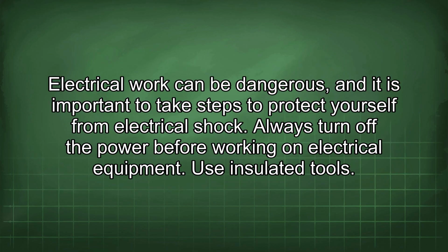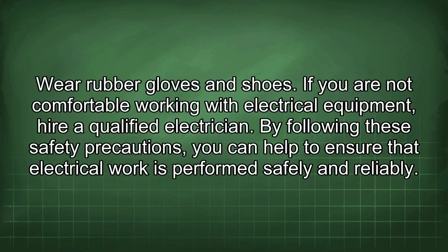Electrical work can be dangerous, and it is important to take steps to protect yourself from electrical shock. Always turn off the power before working on electrical equipment. Use insulated tools. Wear rubber gloves and shoes. If you are not comfortable working with electrical equipment, hire a qualified electrician. By following these safety precautions, you can help to ensure that electrical work is performed safely and reliably.